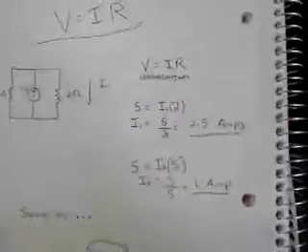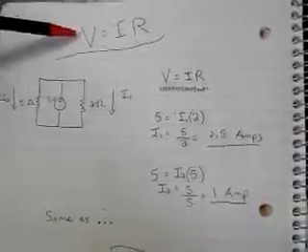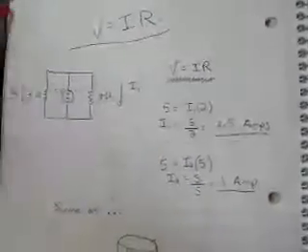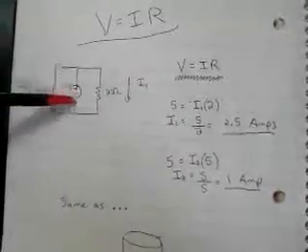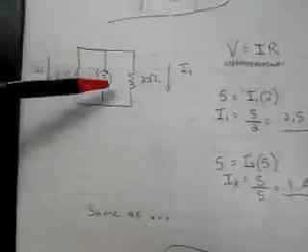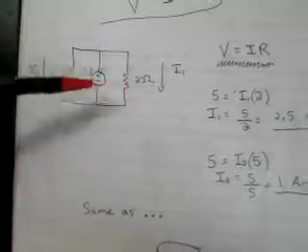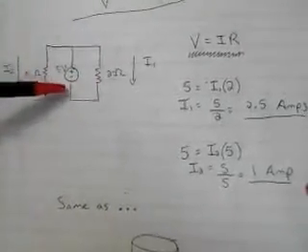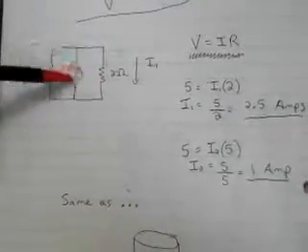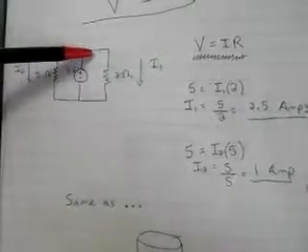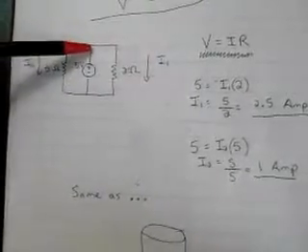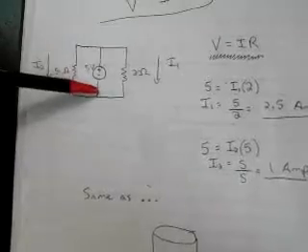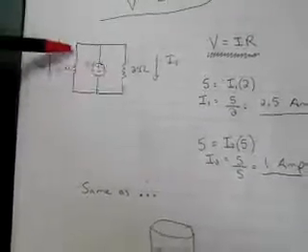So example number 2, V equals IR again, right? We've got a 5 volt battery hooked up to 2 resistors, 2 ohm and 5 ohm, and do note that, don't let this trip you up, there are 5 volts across both of these things, right? From this node to this node, 5 volts across this guy and this guy.